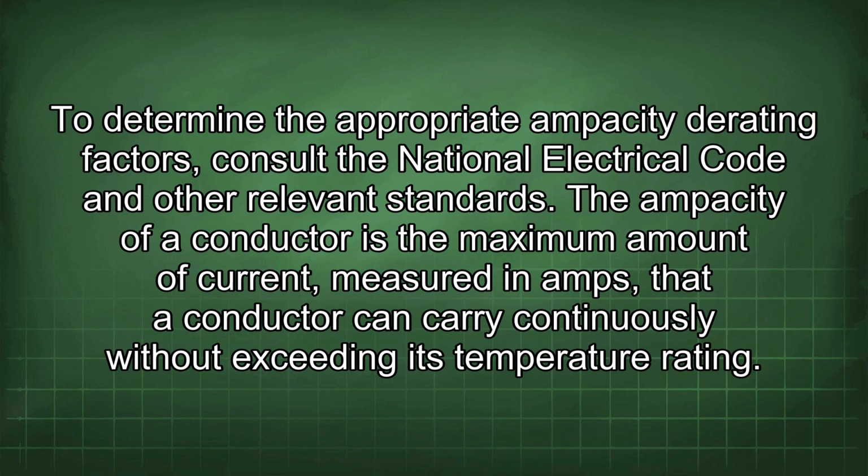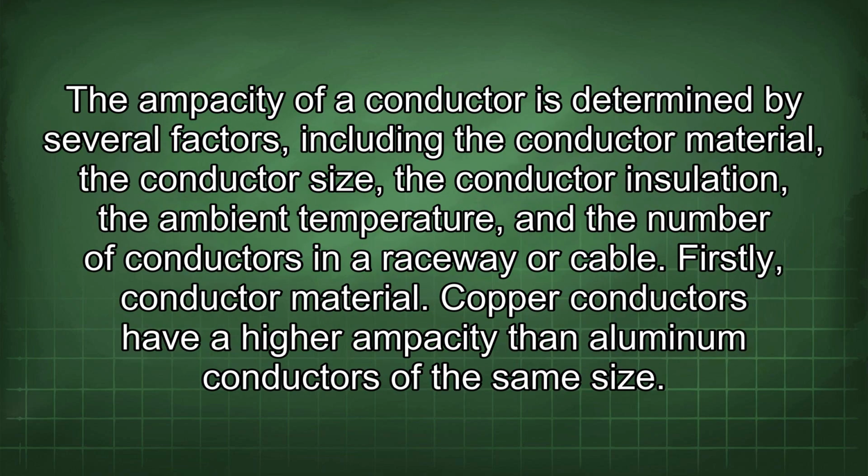The ampacity of a conductor is the maximum amount of current, measured in amps, that a conductor can carry continuously without exceeding its temperature rating. The ampacity of a conductor is determined by several factors, including the conductor material, the conductor size, the conductor insulation, the ambient temperature, and the number of conductors in a raceway or cable.